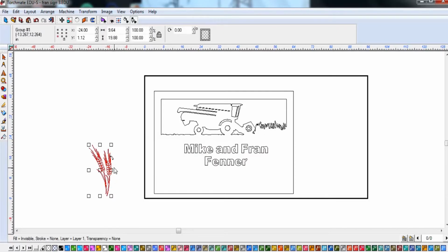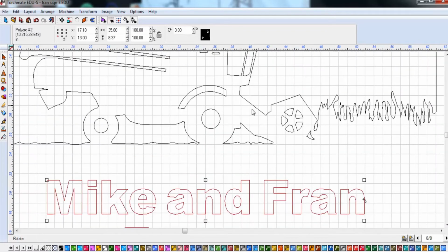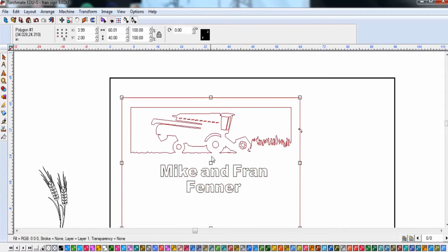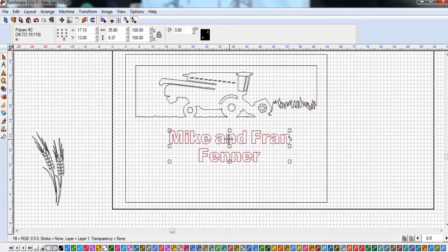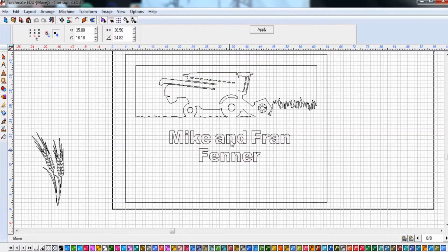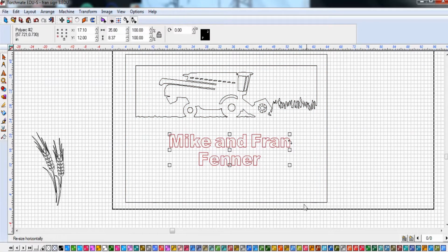Again, this could be made into a path, so I'll just Control H that as well. It was grouped, but now it's an actual path. So the program kind of thinks of it as a separate entity. And that's how I want them to be considered right now until I put them all together. I don't like to move all of them in place and then just make one path and be done with it. I like to make path, break path continually while I'm working on the drawing.